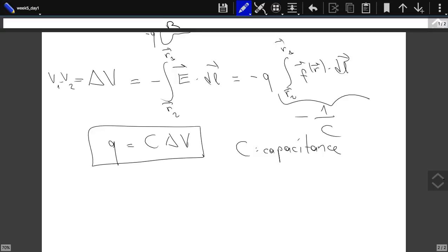But if you increase the electric field, then you are applying a larger force, and after a limit, you can just break these bonds. You can rip off electrons from this molecule. If the electric field is large enough, that is, the potential difference between two points is large enough, you will be ripping the electrons from the molecules or atoms.